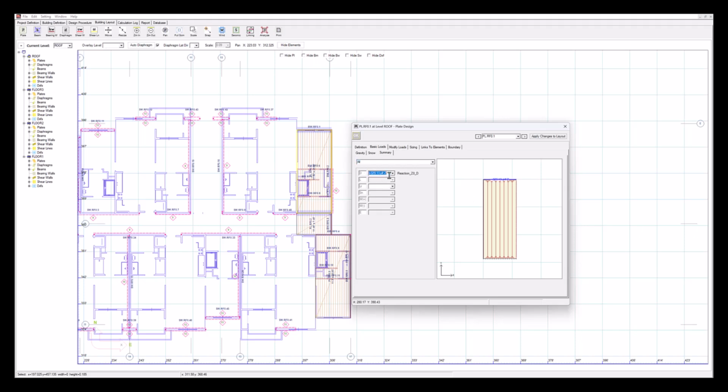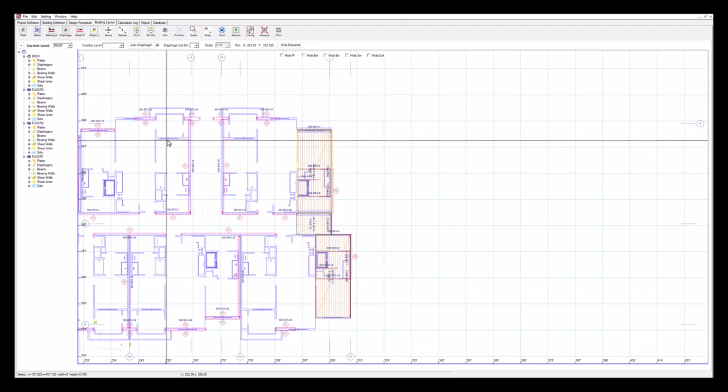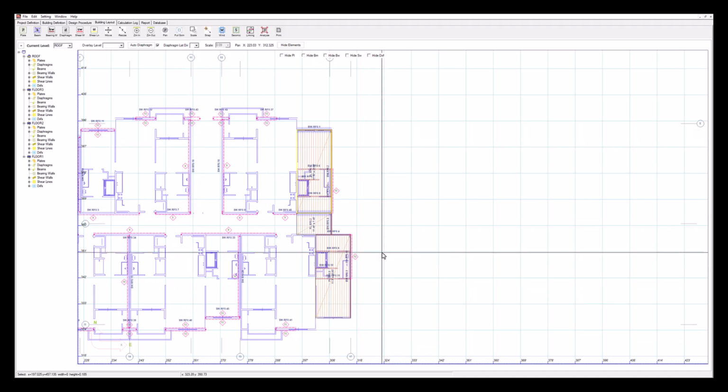So there's about this much going to that side of the structure. If we go to the other side, that much is going down to the other side of that plate, and you can see all the pieces of how this load gets applied directly for that plate. So loads are automatically tracked down the structure, carried from plates for the gravity and diaphragms for the lateral into the beams or shear walls as determined needed into the structure.